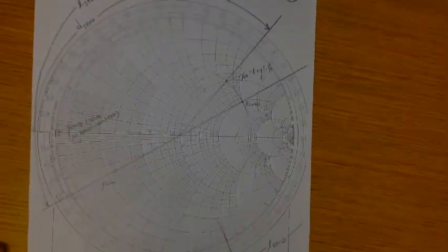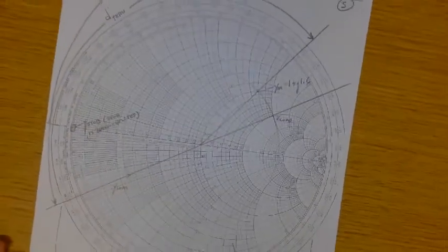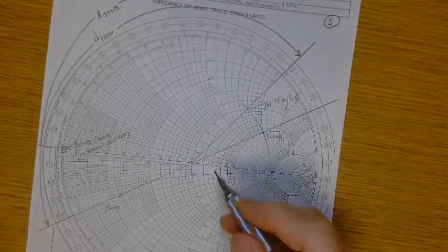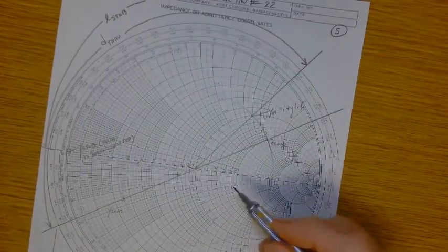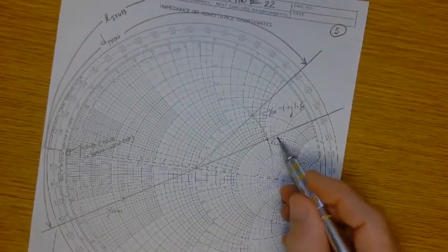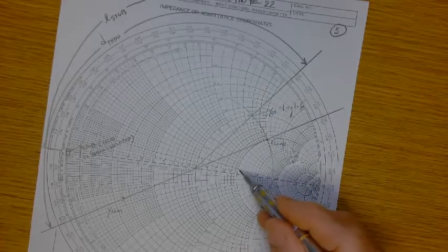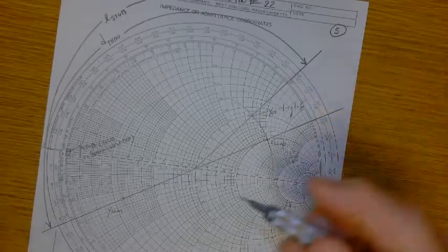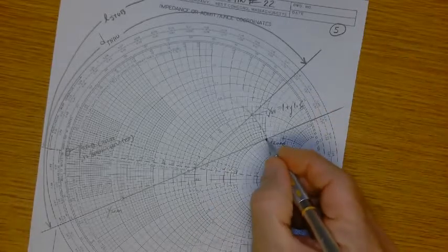Here's the Smith chart. You've seen these before, right? Ugly little things, aren't they? Not really. They're beautiful. Okay, so 2 plus J2. 2, there's your 2 circle. R equals 2 circle. There's your 2 reactance circle. The intersection of those is Z load.